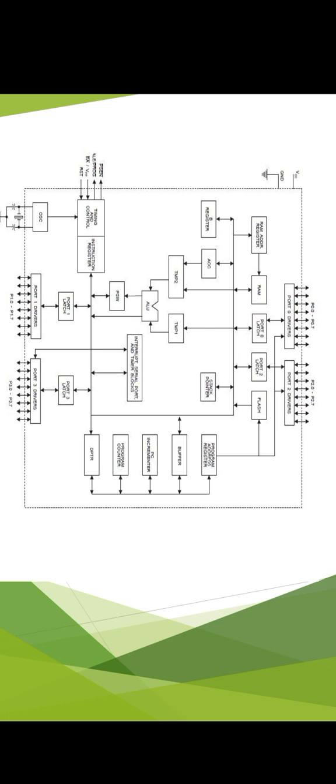These pins are in the oscillator circuit, usually 12 MHz. Then EA. EA means external enable, to enable use of external memory addresses to external ROM. RST means reset pin, reset circuit input, and also resets a few output cycles to the external peripheral devices to let the processor reset and synchronize with devices.